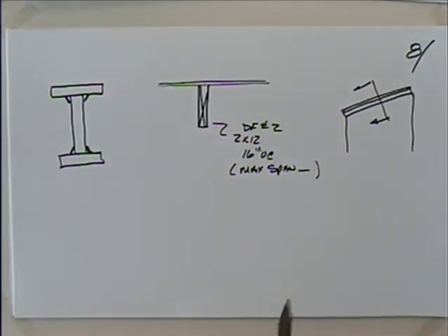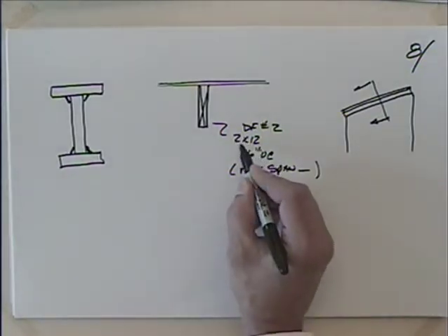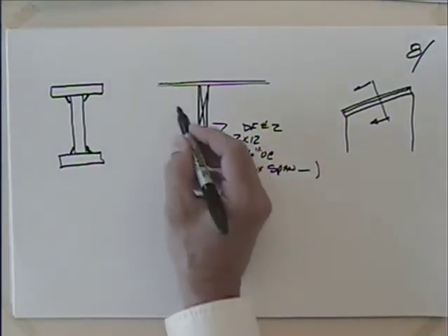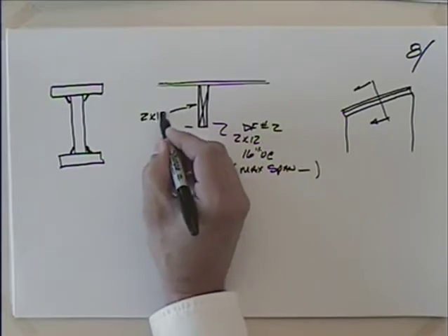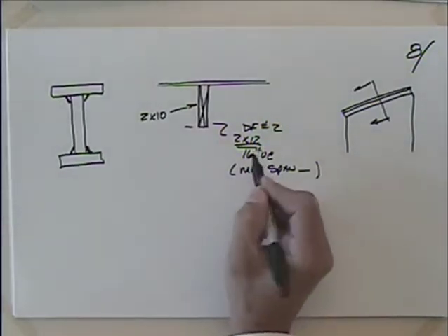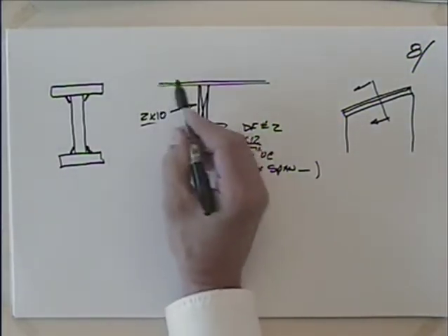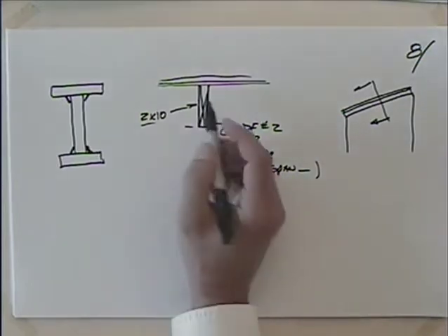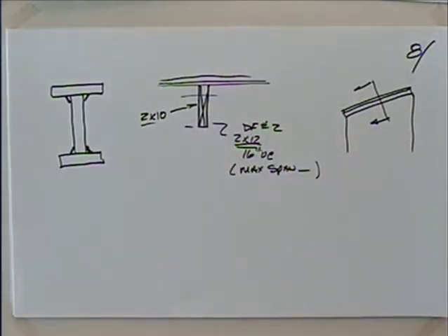Well, I think they must have known more than I did, because they came along and what they put in, they put a 2x10. Okay? That's a pretty long span. And the plan said 2x12. They put a 2x10 in. They nailed this on. They nailed the roof on. It was in the wintertime. They even had the electrician drill some holes and put wires through it. Okay, so tearing this out was not a real easy option.